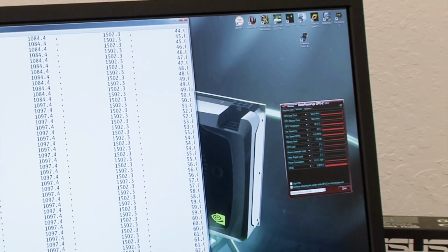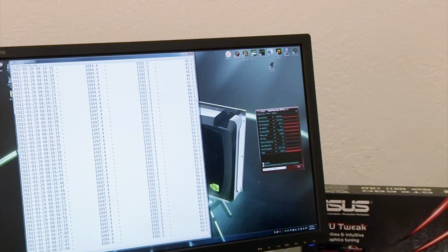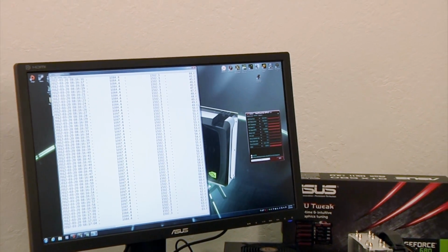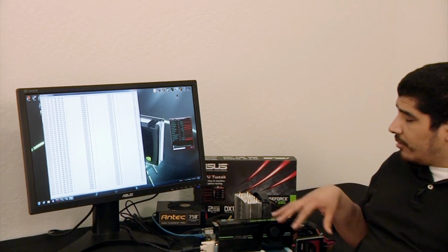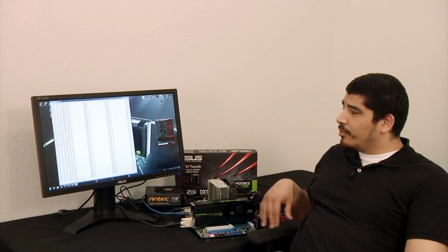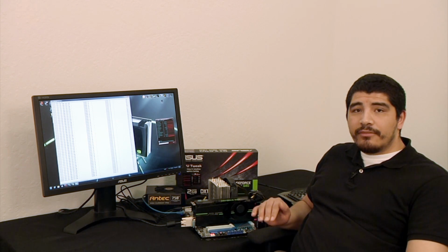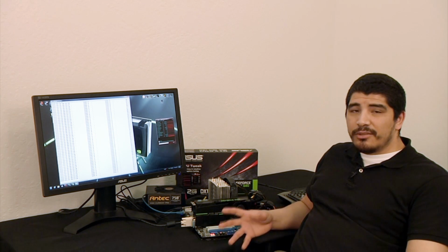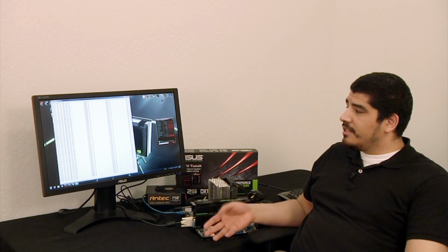If you throw something synthetic on there, something designed just to stress the TDP, you could potentially compromise the integrity of the card and damage it, because you'd be running TDP levels that aren't designed to be handled not only by the thermal assembly, but by the board design itself. But the TDP will block that from increasing. So if you run something like OCCT or FurMark, which isn't advised, you're not going to see these metrics. But under normal gameplay, you're going to get this increase in performance.